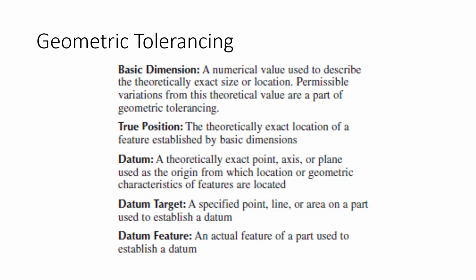I can't use it. So when we talked about tolerances up to this point, particularly last week, we were trying to figure out these maximum shaft diameters, minimum shaft diameters. So we'd have a limits tolerance with the max over the min, and the tolerance was the difference between those numbers. And it had to do with the physical measurement at a precise spot, right? The diameter of that shaft or the diameter of that hole.